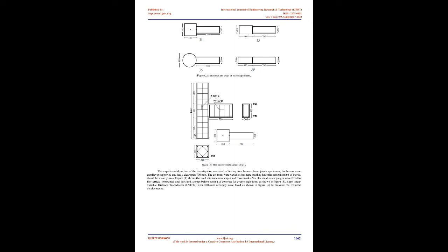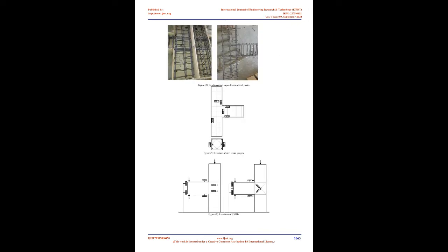Materials characterization. Concrete. Ready mix of normal Portland cement concrete grade 30 MPa was used and tested after 28 days. A dolomite aggregate, AG1 and AG2, with size of 3/4 inch, 19 mm, and 1 inch, 26.5 mm, respectively, was used throughout the specimens. Table 1 lists the proportions of the concrete mix. The design average compressive strength for the mix is 30 MPa.